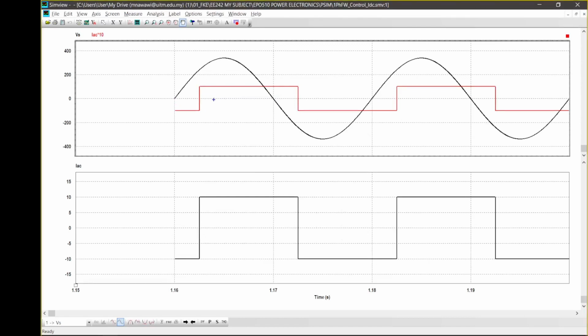So this current waveform actually is made of the fundamental, which is the sinusoidal current. Let's do it again. Okay, the sinusoidal current. So this is IS1, the fundamental component, which is at 50 Hz, and the amplitude here is known as IS1 or C1, with the peak value C1, isn't it?